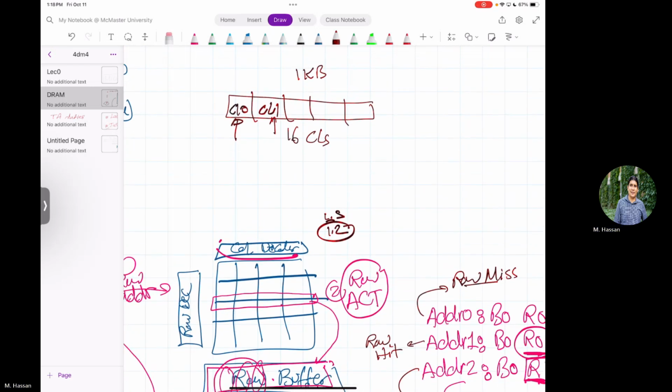So yes, and this is because of an operation of the DRAM that we didn't bring up at all until now, what we call DRAM refresh, right? Because of the charge. The charge, exactly. But I will discuss this in a second. After a refresh, everything is just as if you booted up, so all your rows will be idle in the banks.